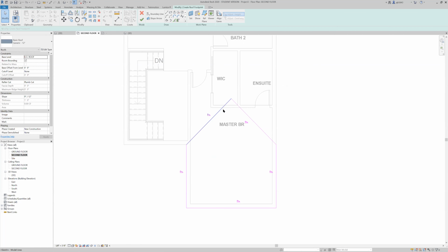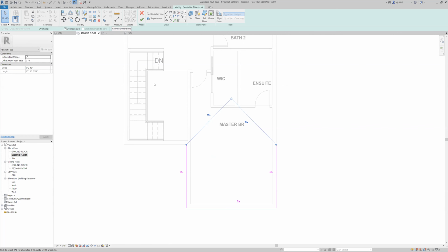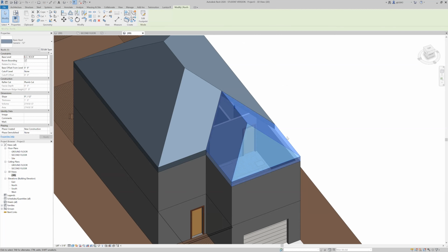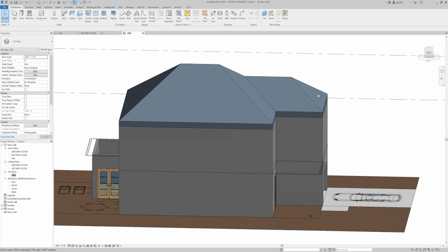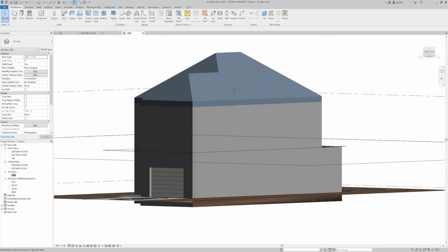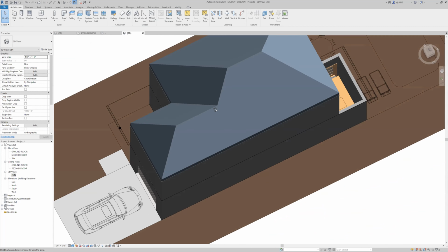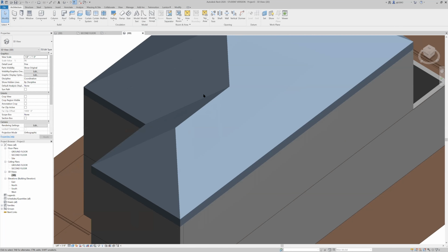And then we want these to be vaulted. And then I can show you the difference whether or not we want this front one to be vaulted. So I'm going to go ahead and uncheck define slope and accept the sketch. So if we go back to 3D mode, you'll notice that this front roof looks similar to the back slope, that they are identical. Using a 45-degree miter for this is probably one of the easiest ways.